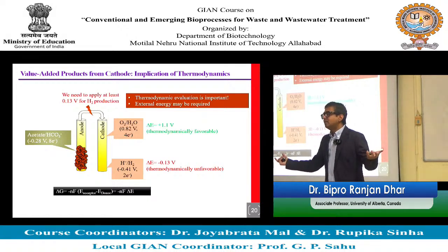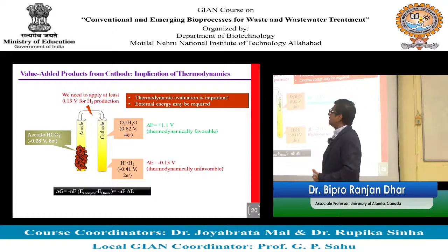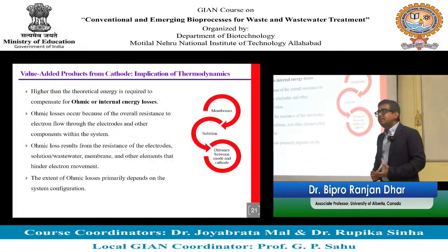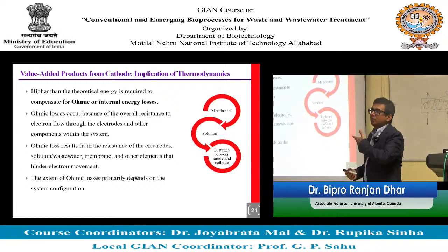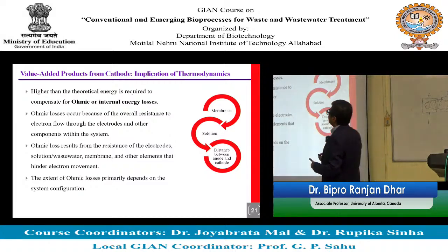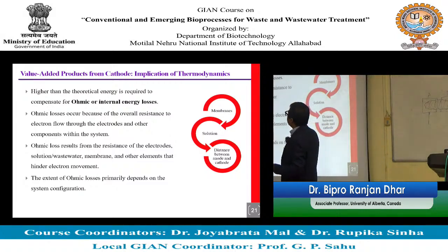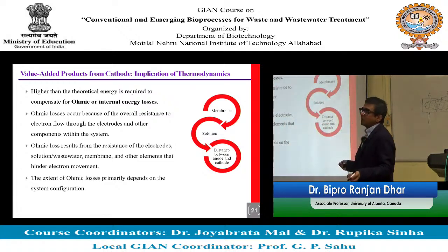No. Why? Because there are going to be some other energy losses in the system. There is going to be other resistance in the system that creates a barrier for electron flow, right? So there are going to be more energy losses, and those energy losses we call ohmic or internal energy losses. They can be contributed by different components in your system.